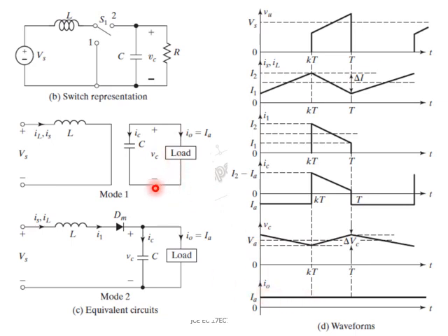And that is flowing through the capacitor in this direction, and hence it will be the reverse current flowing through the capacitor. So in the capacitor waveform, this IA will be represented as negative IA, because the current flowing through the load is IA but in the reverse direction. So this is basically your mode 1.